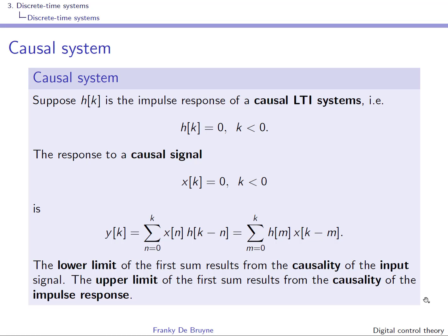We have just shown that the response of an LTI system, given its impulse response and the input signal, can be computed as follows. Y of k is an infinite sum, n going from minus infinity to infinity, of x of n h of k minus n.